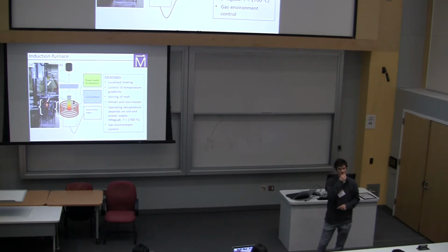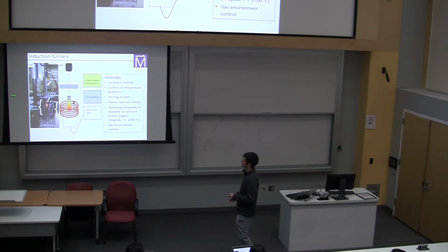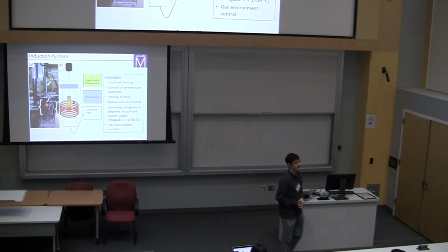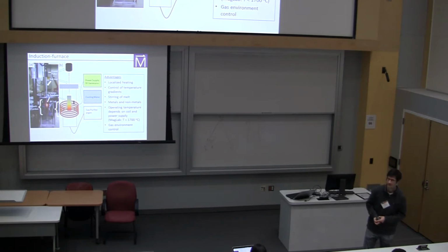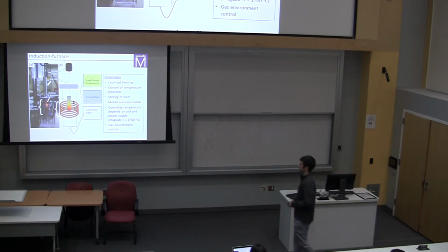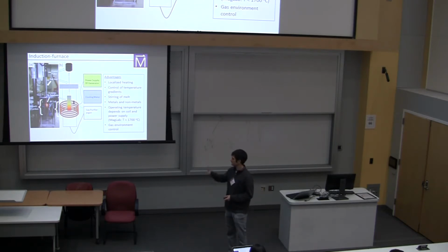Nevertheless, we should evacuate this tube in a quartz, so it should be connected to a static or dynamic vacuum or something. I'll mention again, the way we have it set up, vacuum is fine, but I think it's easier and possibly even better to run this at an overpressure of purified argon, right? And the reason I think that's better than vacuum is that if you want to have an extremely good vacuum that's truly going to protect your crucible, you probably can't get away with rubber O-rings, right? You probably need to make an ultra-high vacuum environment.